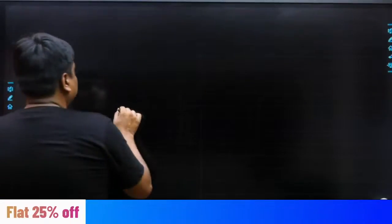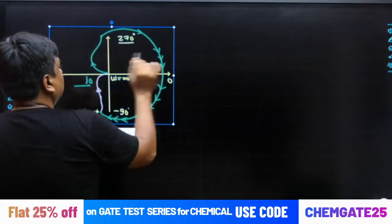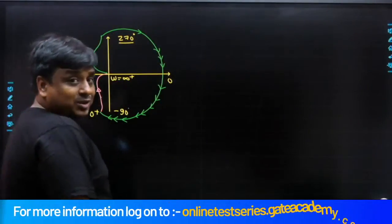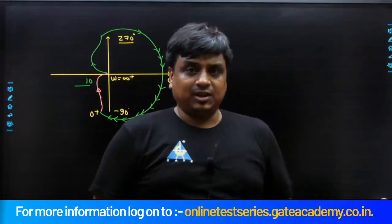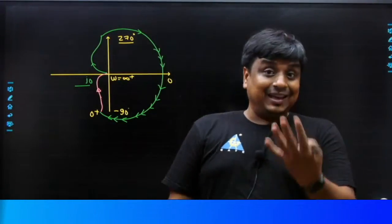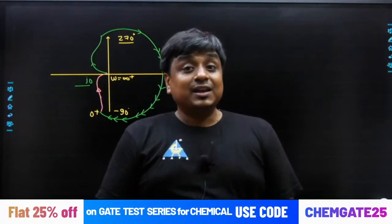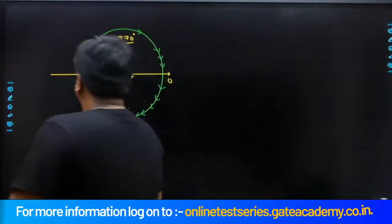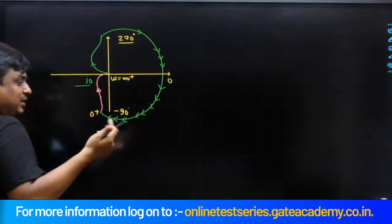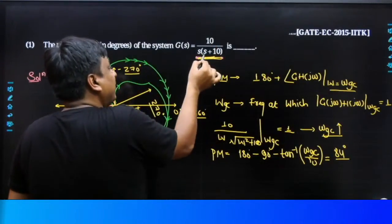See what has been happening over here. What does phase margin mean? How much phase lag we can introduce into the system such that the system reaches the verge of stability or instability. If we talk about gain margin, how much gain we can pump into the system such that the system would reach the verge of instability. If you keep pumping the gain, what does pumping the gain mean? Here you have 10 divided by s plus 10, no?